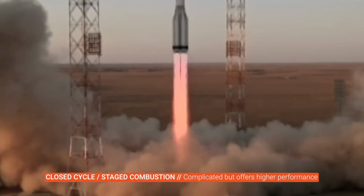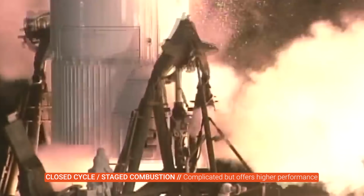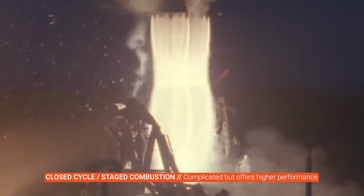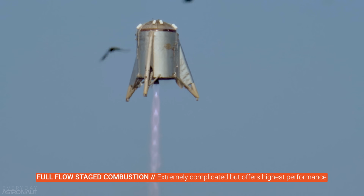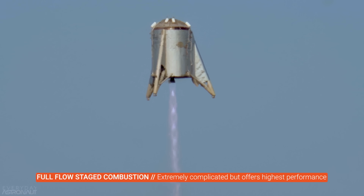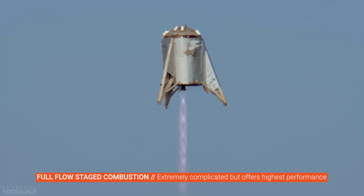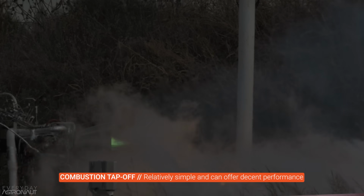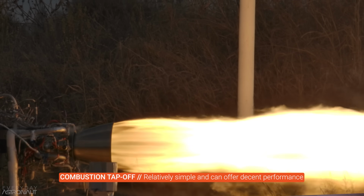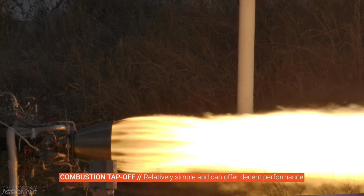Closed cycle has always been much sought after, and the Soviets made it look easy. Gains over open cycle engines should be expected, but with extra complexity and some new issues. Full flow is easily the most complex system, but has the potential to run the coolest turbines and the hottest chamber, which can definitely help it reach ridiculous levels of thrust. Tap off, I'm actually surprised we haven't seen developed more. It seems like it's, again, relatively simple and reliable, but it can actually still reach high levels of performance.